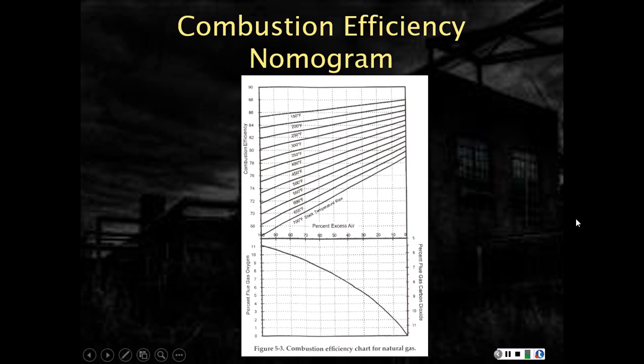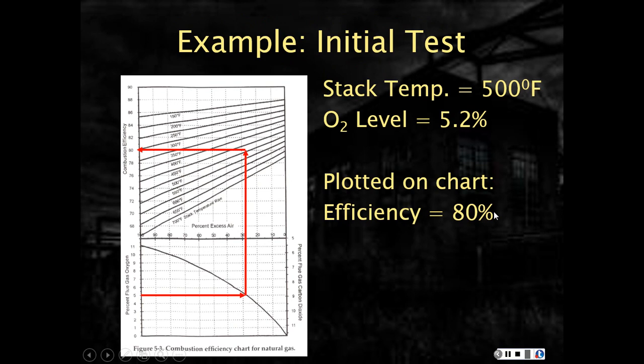Now, most problems assume that I'm going to start making adjustments to my excess air to try to increase efficiency. Now this may or may not impact my exhaust gas temp or stack temp. It'll certainly affect my percent of gases that I'm measuring in the exhaust gas.